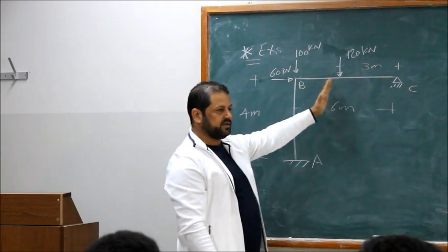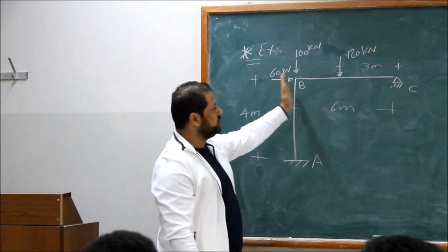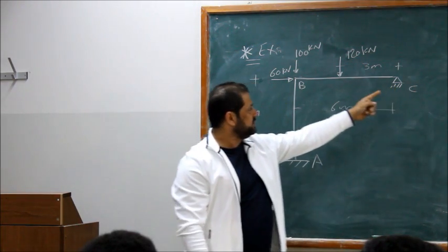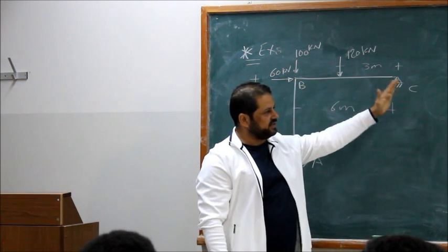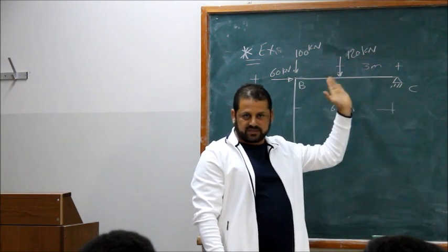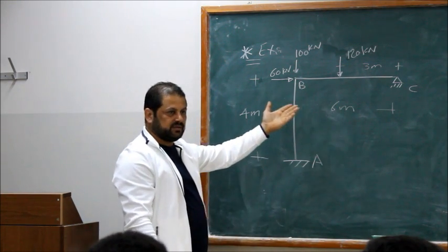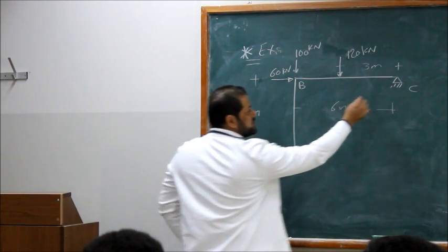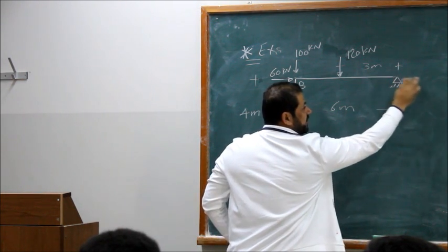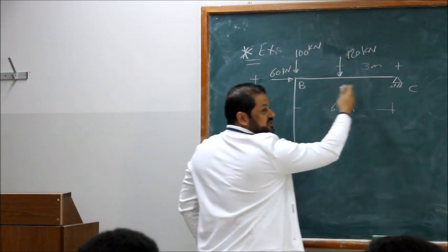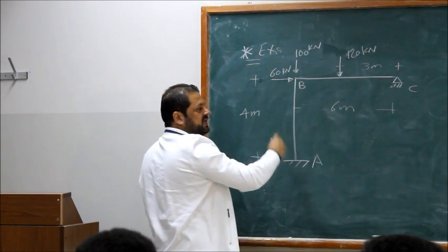If you look at this one, can this frame under lateral load go to the right? No. It's restrained by this pin and it cannot sway to the right. So side sway is prohibited, or not allowed. But if we have this one roller, this one can move to the right, so there will be a sway. The frame will be a sway frame, or side sway is allowed.